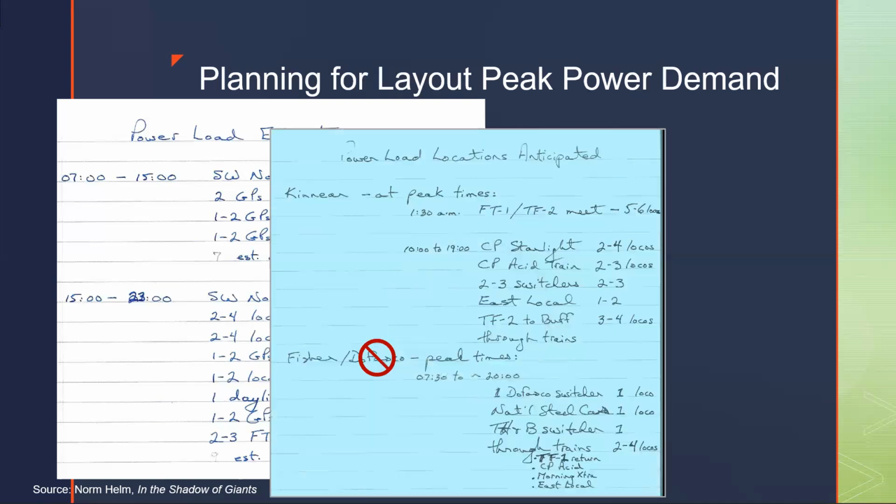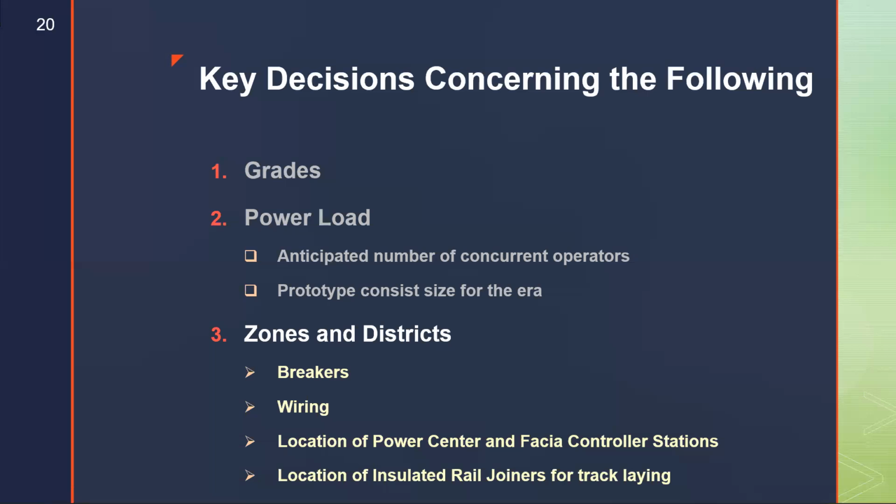Once I knew what the jobs were, it's a question of where were they concentrated on the layout and how might that influence the way I lay out the electrical plan, and then how would that translate into the laying of the track. So we end up with a power center under my layout, a repurposed kitchen cabinet. Each of the decks of my layout is its own separate zone, isolated from the other, each with its own power supply, and I use NCE equipment. Each booster is rated at a total of 5 amps.